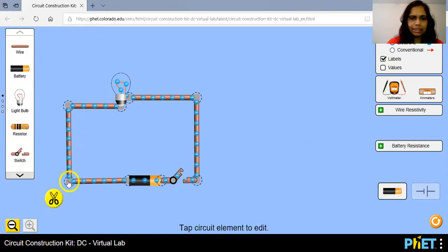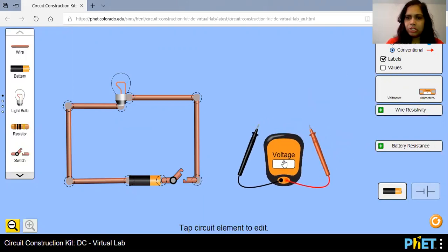All right, so I connect the circuit and I see here the switch is open. That's why we don't see a current flow through this. Anyway, if you look on this side of the simulator, you can see show current, right? We can see either electrons or conventional current. As you know, conventional current direction is opposite to the electron flow. And this is a voltmeter. If you want to measure the voltage across any element, you may use this one. And the voltage unit is volts, right?